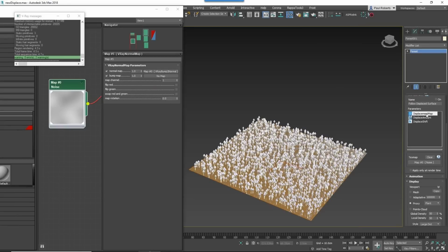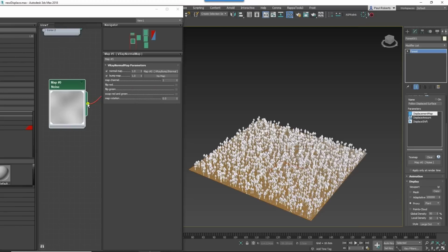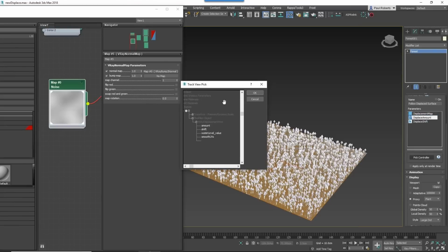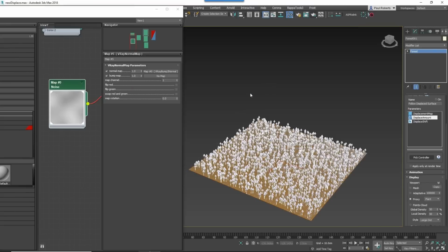And you can see in Forest, this Forest effect has a map input, which is a new thing in Forest Pack 6. So I can pop the same displacement map in there so that it knows what the displacement is going to be. And for the displacement amount, I can actually link Forest Pack to the Displace modifier on the surface. So I just link Forest Pack to the displace amount and then turn this effect on.